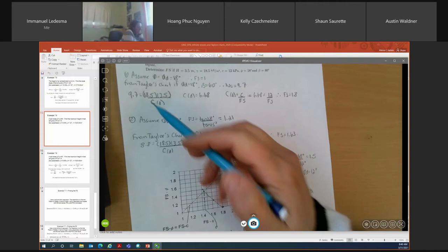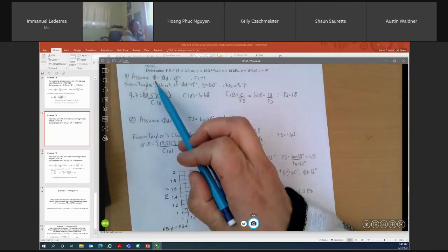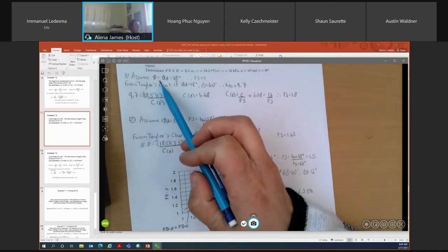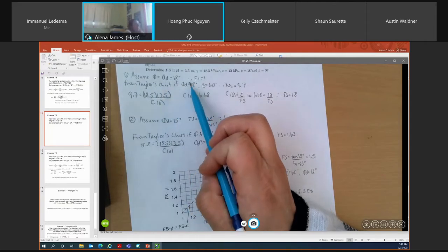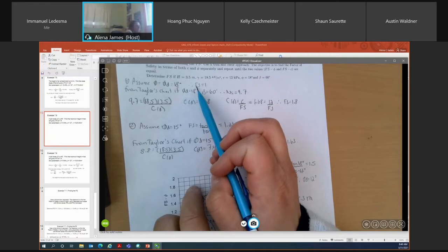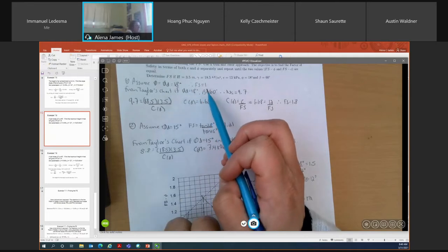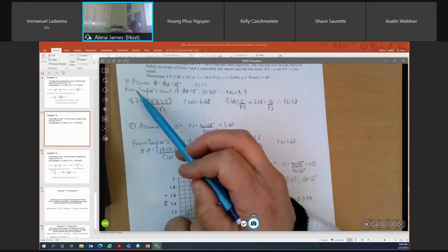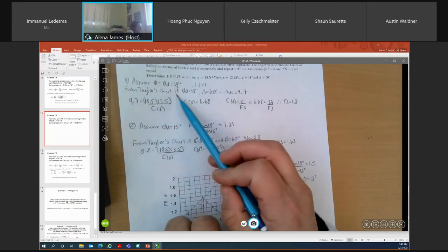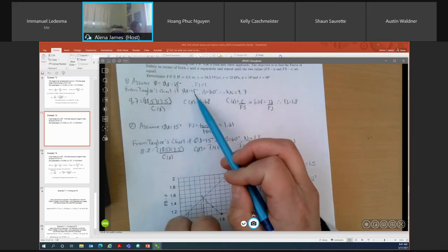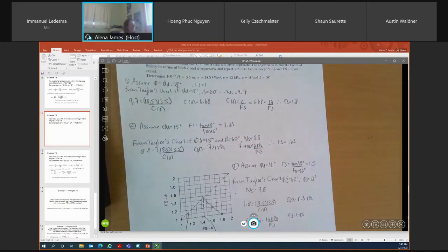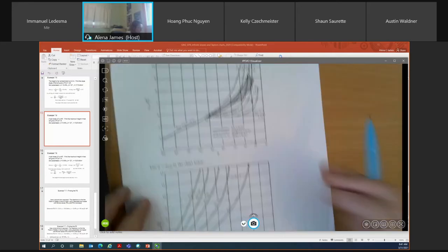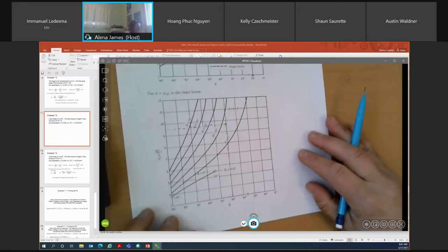In this example problem, our friction angle was 18 degrees. So I'm going to assume that my phi d value is also 18 degrees, and therefore my factor of safety for my friction angle is equal to 1. So I can use my Taylor's chart at that point. If I know my phi d value is 18 and my slope angle is 60 degrees, I can determine my NS value. I'm going to use the bottom Taylor's chart.